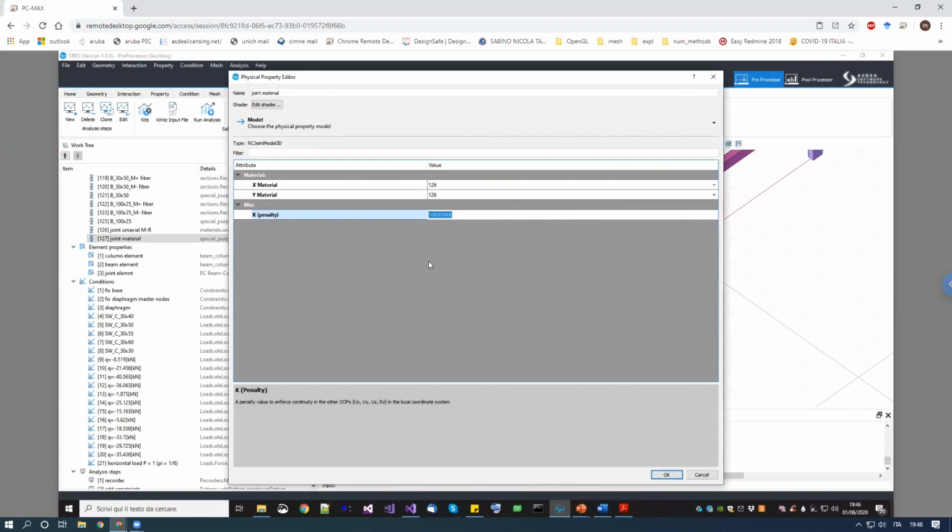So how do I do it? Since this one basically will be in series with the stiffness of the beam, you can choose a value which is, let's say, a couple of orders of magnitude higher than the beam bending stiffness, for example. Now, in this case, my concrete model has a stiffness of 3 to the power of 8. Then the largest bending stiffness of our beam, moment of inertia, was something to the power of -3, or -2, sorry. So it was to the power of 6, and then I have 2 orders of magnitude, okay? Now it is sufficiently stiffer that the one that will deform in that degree of freedom will be the beam, okay?